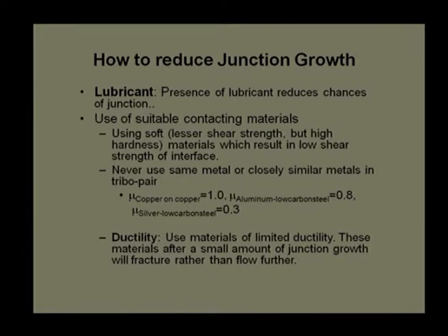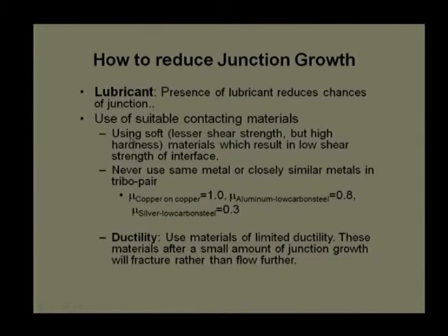surfaces. It's something like when we play carom board, we use powder lubrication. We provide a powder form, a similar kind of action which has a loose structure with low shear strength, that will work here. And there is a possibility to choose an appropriate material. We say that when you choose a soft material as a third material, it may provide a low shear strength, and that may work.